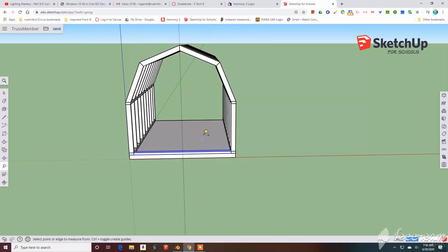All right, so now I'm going to simply drag over some more guidelines here, and notice how I'm dragging in the x-axis. The red arrow is indicating I'm dragging in the x-axis. So I just want to click over to the right here, and I'm going to set that at 16 inches. So I type in 16. And then I'm going to do the same for the opposite side.